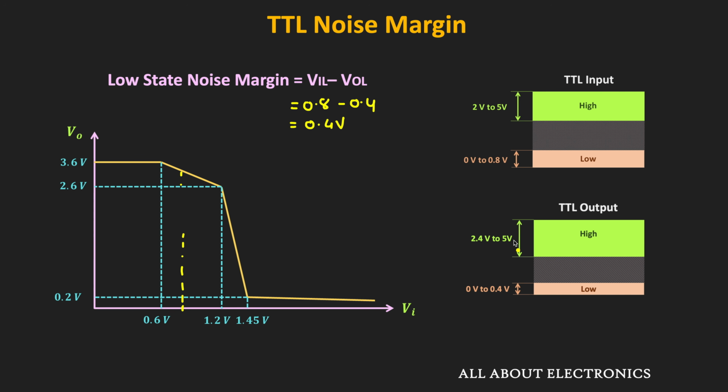So as per this voltage transfer characteristic, when the input is equal to 2 volt, at that time, the output is around 0.2 volt. Or we can say that is equal to logic 0. That means whenever the input is equal to VIH, at that time also, the circuit will work properly. And here if you observe, then even at the 1.5 volt also, we are getting the logic 0. But considering all tolerances, this TTL range is kept more conservatively.